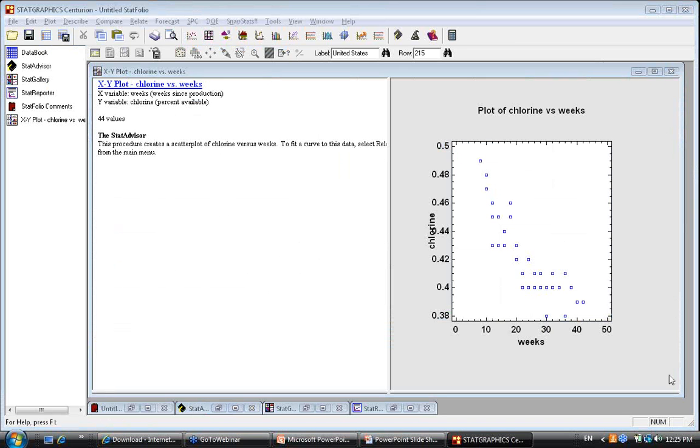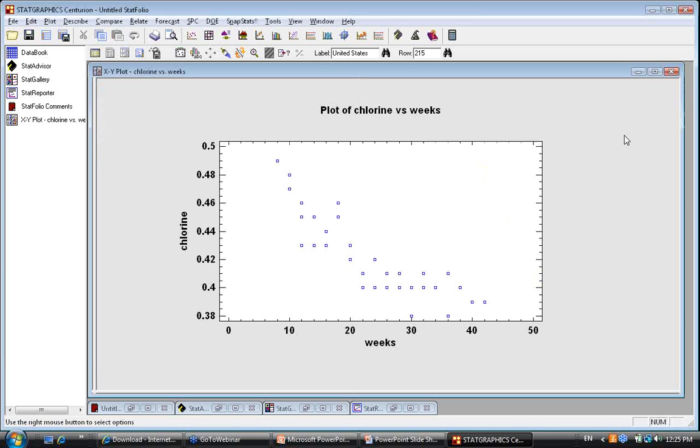Whenever you get a scatter plot, if you want to add a smoother to it, you first double-click on the graph to make it large. You then go to the analysis toolbar, that's the lower of the two toolbars, to an icon that has two arrows and some points with a smooth line. Now, this actually has two uses. That's why it looks so strange. It smooths a 2D plot and rotates a 3D plot. We saved a little real estate by doubling up the function of that button.